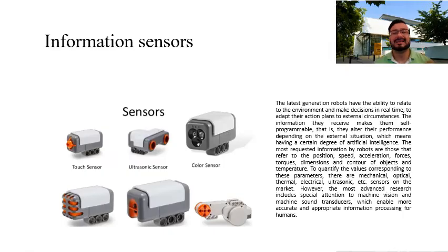Sensors used in industrial robotics can be classified into two categories, internal and external. Internal sensors are components of the robot and are used to control the position and velocities of the robot joints. The sensors form a feedback control loop with the robot controller. Typical sensors used to control the position of the robot arm include potentiometers and optical encoders. Tachometers of various types are used to control the speed of the robot arm.